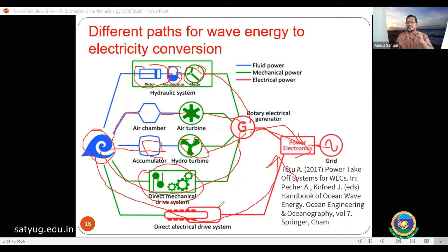Okay. So in that case, what they are doing is putting coils layer by layer, 1, 2, 3, 4, 5, 6, 7, and moving a magnet up and down. The magnet will be connected to the wave. When the magnet is moving up and down and the coils are around it, the coil will get EMF. That EMF, or electricity, you can collect and produce electricity. So that is called a linear generator based electricity generator. Instead of a rotary generator, you are creating a linear generator, and you are producing power.